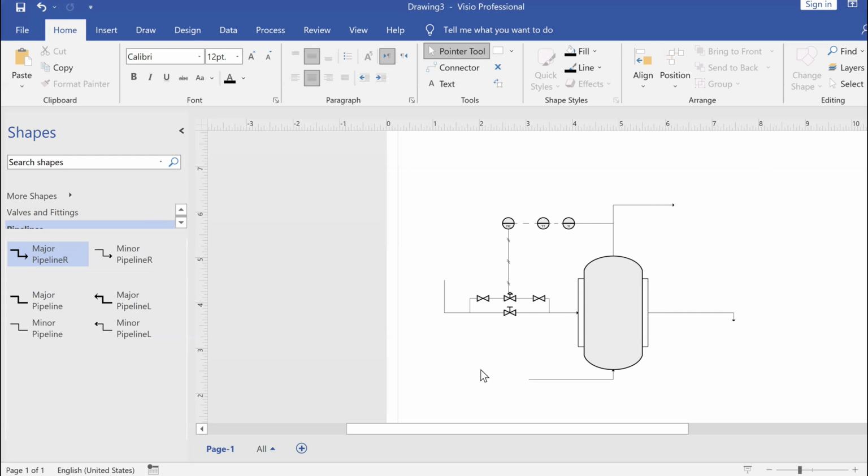That means the cooling jacket is overloaded, it's doing extra job. What happens? The controller will send a signal that this valve must reduce the flow rate, decrease the opening of the valve, decrease the flow rate of the cooling water entering the cooling jacket, and therefore the temperature rises to the required temperature.